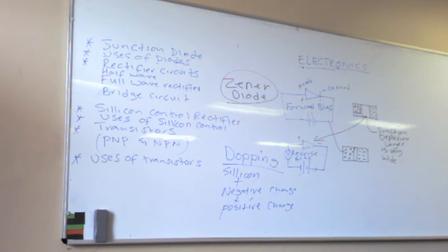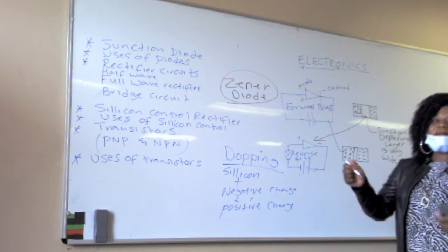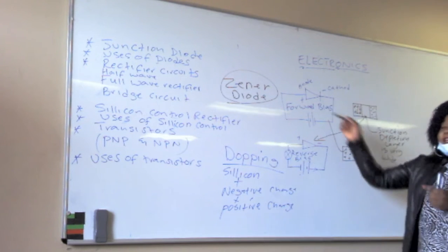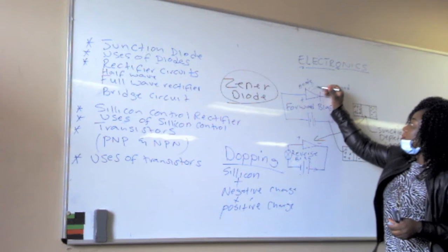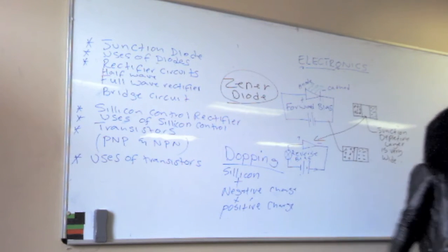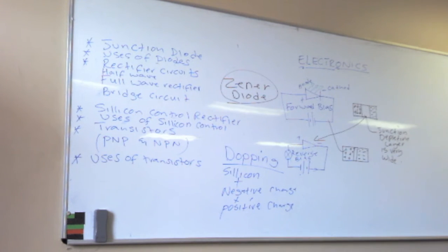I think you know, I've got one of them there. It looks like a globe, but it's not a globe, it's a diode. With the light emitting diodes, it looks like a junction diode, but it's got arrows like that. The arrows are indicating that light is being emitted when current passes through the diode. That's why they say LEDs. In forward bias, it's going to function. In reverse bias, it won't, because current won't cross the diode.